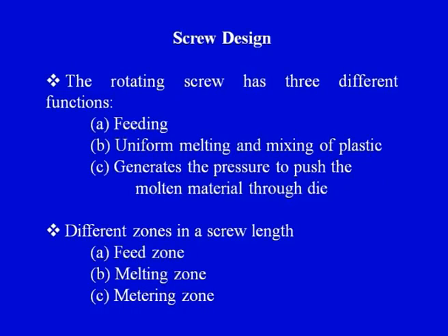Now, the different zones in the screw length, because if you remember the diagram, there was a definite length of the screw. This length can have different zones. There can be a feed zone, a melting zone, and a metering zone, which we have already discussed.